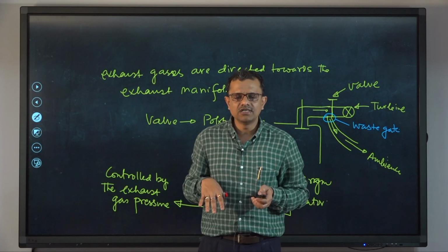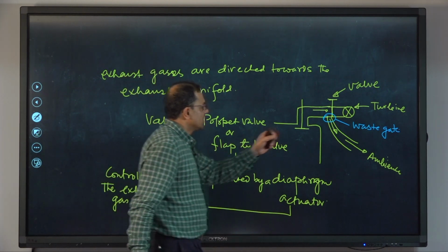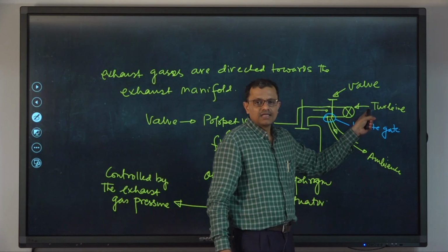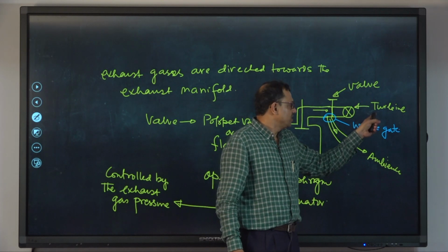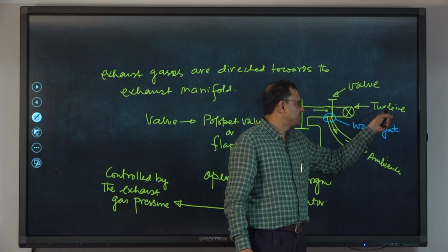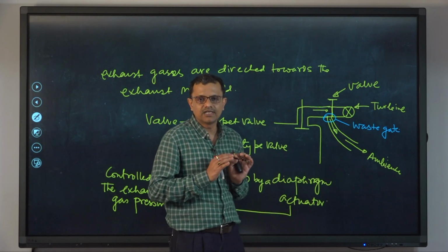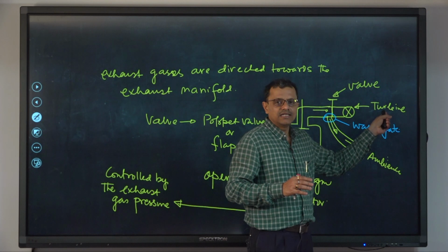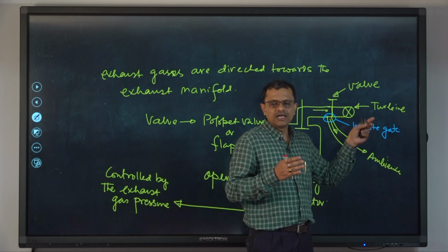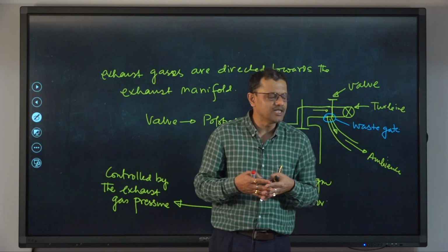So, that is what we wanted to discuss. That means, if we need to use a fixed geometry turbine for any particular requirement, knowing fully that a fixed geometry turbine will have two different problematic issues. Rather, having one fixed geometry turbine in a turbocharging unit, there will be two problematic issues, and those are overspeeding and overheating.